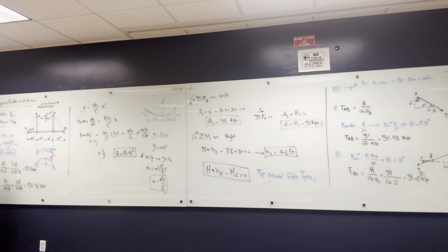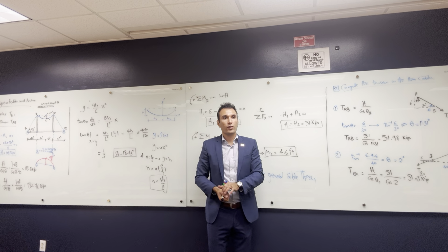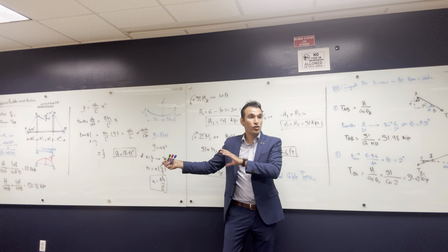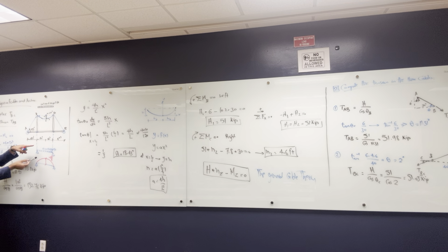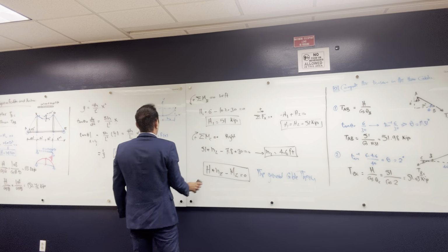Does anybody have any questions? So right now in cable problems, what you are going to do is try to figure out how to apply the general cable theory. Try to draw the beam that is equivalent to this cable and use the bending moment on this beam with the given heights in your problem to figure out what the horizontal force is. Okay, so that is for cables. Let's now talk about another topic.